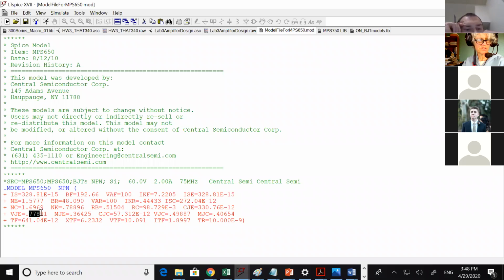Okay, like 0.777 or so. Okay, so that would be 2.23. If you put 2.23 volts across a 438 ohm resistor, what do you get, just out of curiosity? 5 milliamps. Oh. Okay, so if you're picking 1 milliamp as your current, then there has to be some massaging going on between these two. I didn't fully vet this problem, so I apologize.